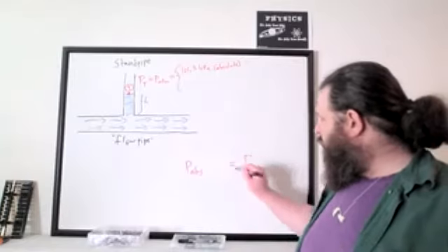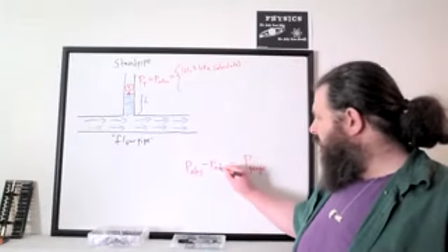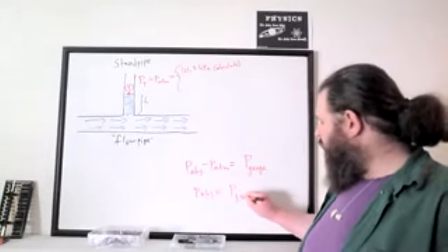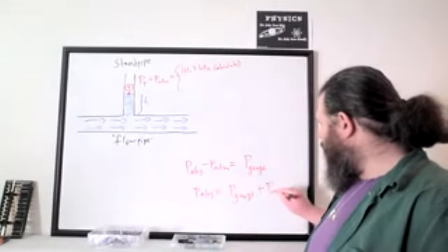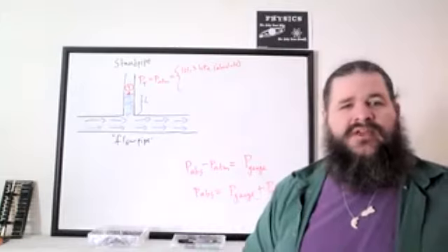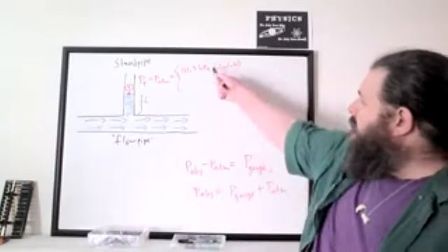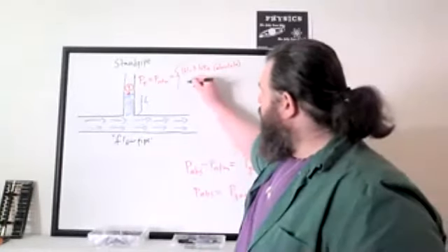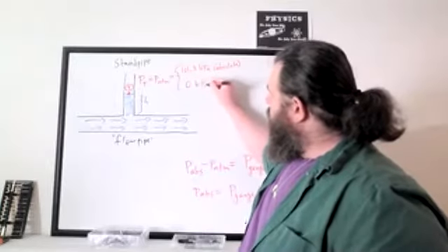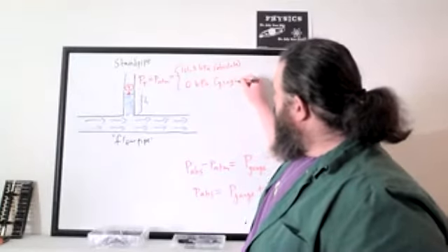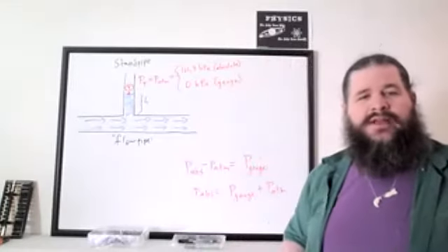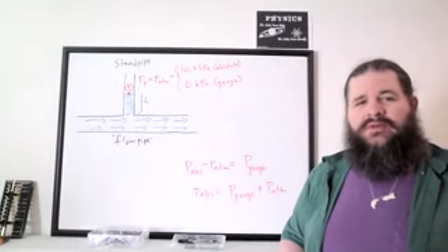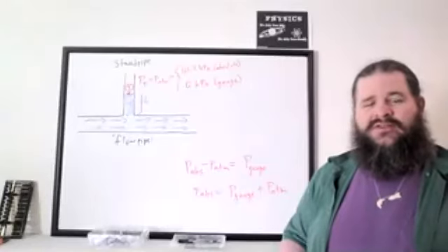Yeah, exactly. Because the gauge pressure is absolute pressure minus atmospheric pressure. Or to put it another way, absolute pressure is gauge pressure plus the atmospheric pressure. Because atmospheric pressure is basically just a convenient reference point. If you take the absolute pressure and subtract 1 atmosphere, you get the gauge pressure, which in this case would be 0. So gauge pressure basically just means we're calling the atmosphere 0 and then measuring everything relative to that. Because in most cases, we don't really care how much pressure there actually is. We just care about differences in pressure.